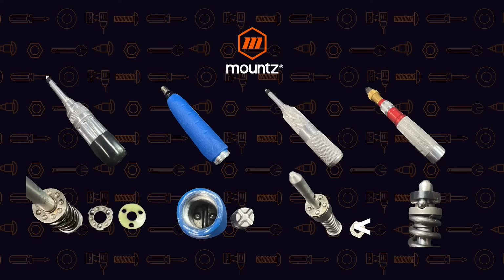And then finally, we have the same type of mechanism as this one, except this is a little bit different, where it's at the back end of the tool, and again the ball bearings will remain in their lobe, and the arm will come and push those ball bearings down, compressing the spring and allowing the torque to be achieved.